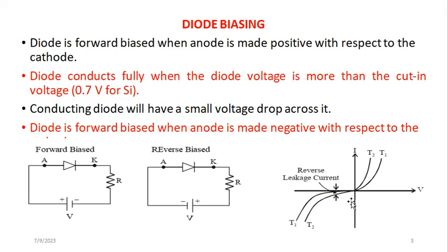And this is the characteristic curve that shows the conduction when it operates in forward mode and in reverse mode. The diodes are normally made using either silicon or germanium. If you have a diode made using silicon, there is a minimum forward voltage that will make it start conducting, and that is what we call the cut-in voltage or turn-on voltage.